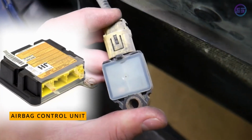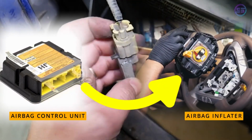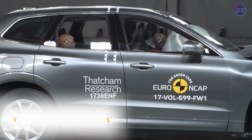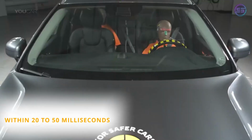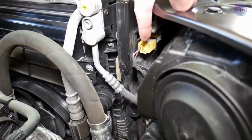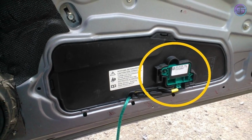When the control unit determines there is an accident, it sends a signal to the inflator system. The inflator immediately fills up the airbag. This all happens in an instant, usually within 25 to 50 milliseconds. This airbag provides a cushioning system for the people in the car and saves lives. Crash sensors are located in the front side of the car, behind the bumper, and also inside the side pillars or doors of the vehicle's body.